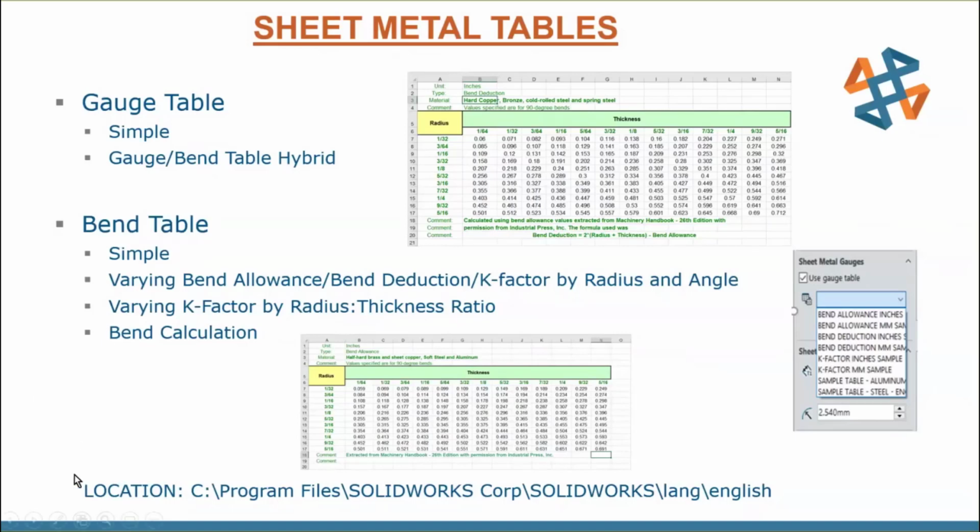And then the main thing here, guys, is the location of these tables or templates right there in your C program files, SolidWorks Corp, SolidWorks Lang English, okay? And when you do open that up and do a file save as, just make sure it's in that location so you can get to that pull down, and you'll see that here in a second.